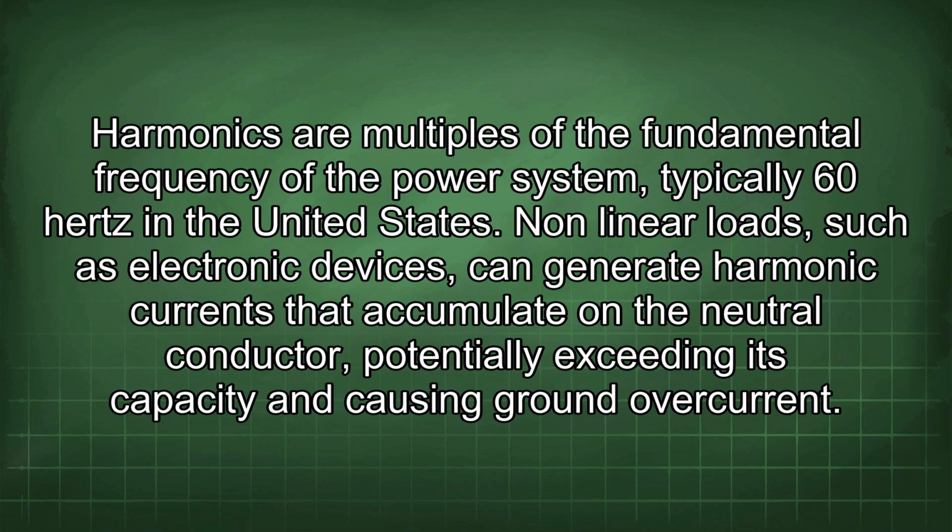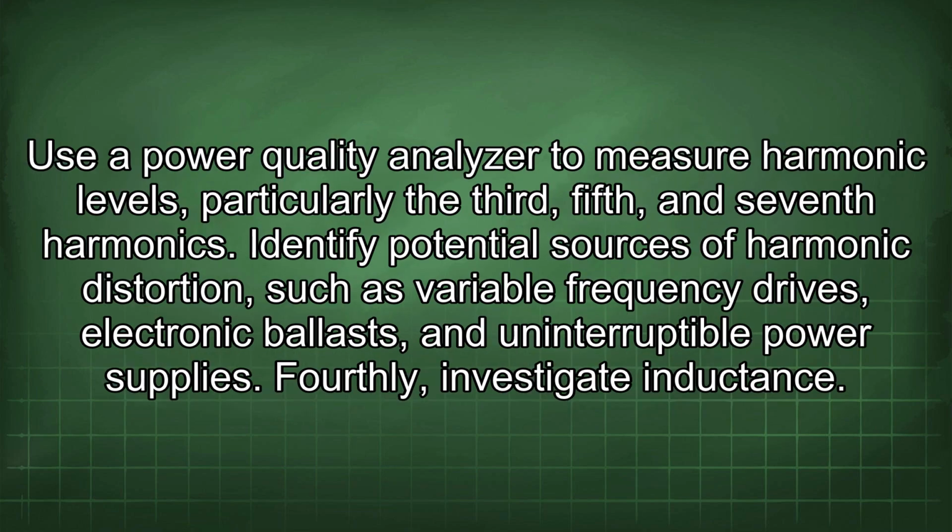and causing ground overcurrent. Use a power quality analyzer to measure harmonic levels, particularly the third, fifth, and seventh harmonics. Identify potential sources of harmonic distortion, such as variable frequency drives, electronic ballast, and uninterruptible power supplies.